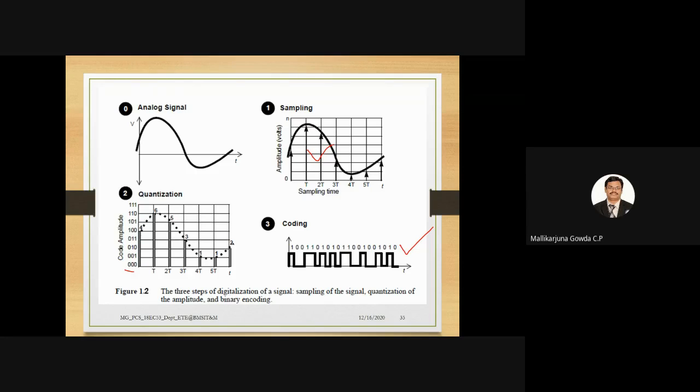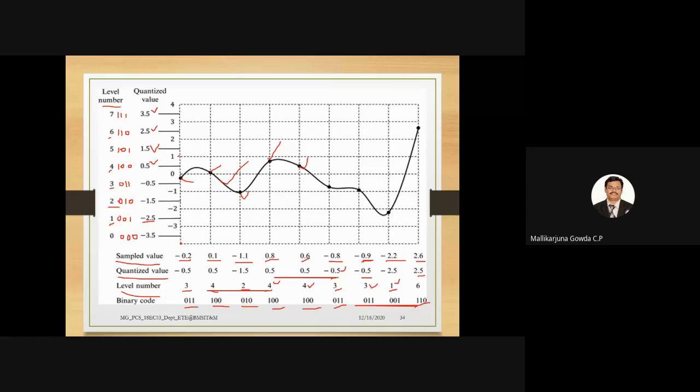Right? Is this clear? So this one example will be more than enough for you to explain what PCM is. So you can take any random waveform m(t), sample it, quantize it, represent the number of levels and its quantized value. Then you can write its nearest sample value by rounding off to the nearest quantized level. Then its equivalent binary code. Yes, if you have any doubts, you can ask about this.